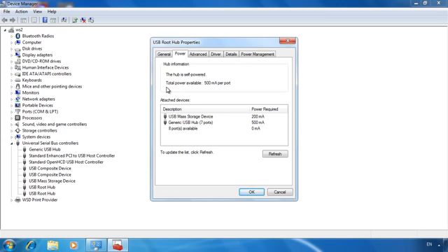This is a little misleading because, as you can see down at the bottom, there is one device plugged in and 7 free ports. The USB thumb drive plugged into the computer is using the port and 200 milliamperes of power. If I were to plug a USB hub into this port, I could run 8 ports off that hub. In simple language, it is saying this port can support 8 devices with 500 milliamperes for each device.